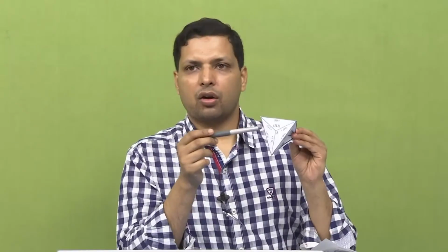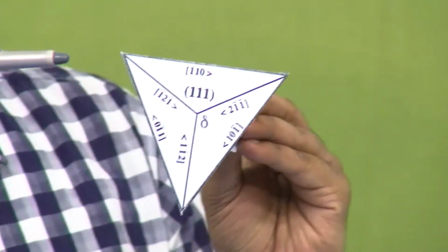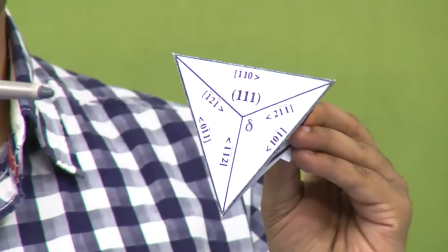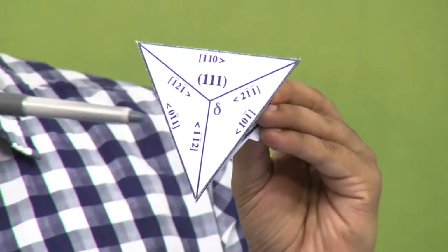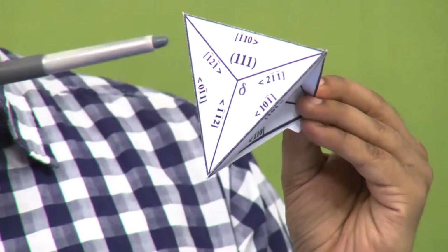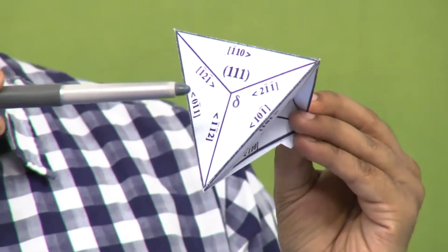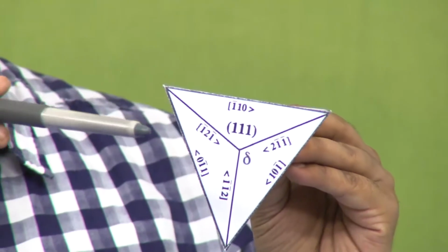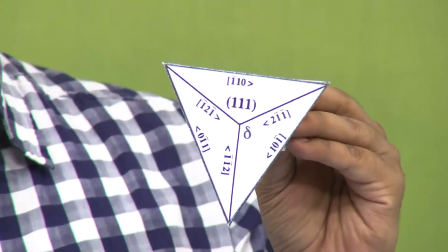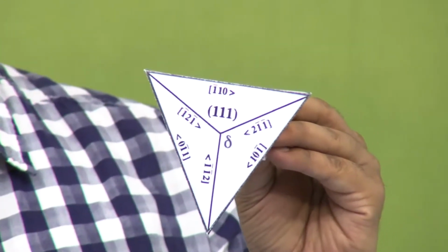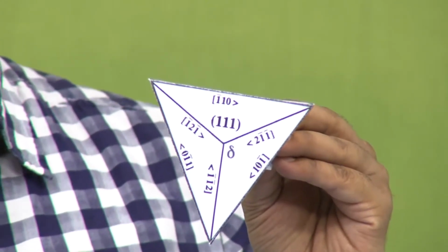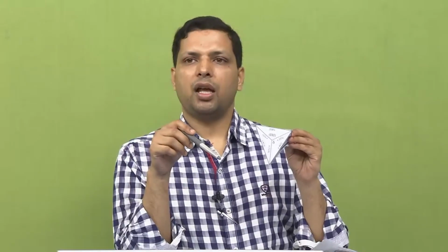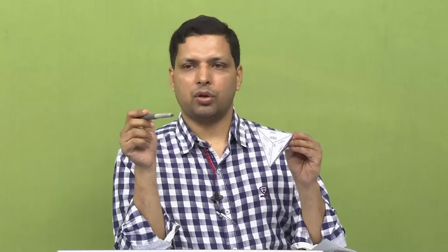So, there can be a cross slip of dislocation, and when we talk about cross slip, it has to be screw, you just keep that in mind. So, a screw dislocation with this particular Burgers vector can cross slip only onto this, and you remember we solved one example where we showed that there was a dislocation moving from P1 to P2 to P3, and when we said that P1 and P3 have to be the same, there cannot be any other possibility.